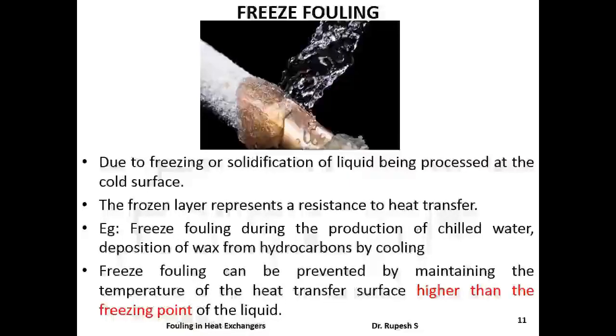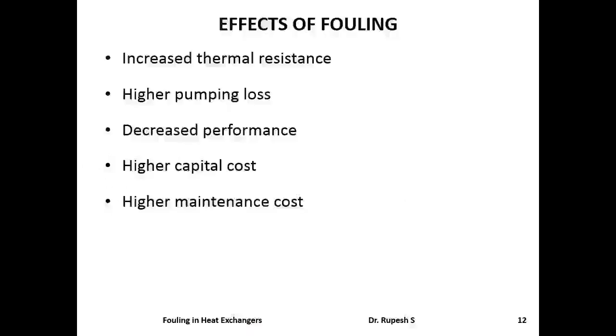As this occurs due to freezing, this fouling can be prevented by maintaining the temperature of the heat transfer surface higher than that of the freezing point of the liquid. Now let us see what are the main effects of fouling.